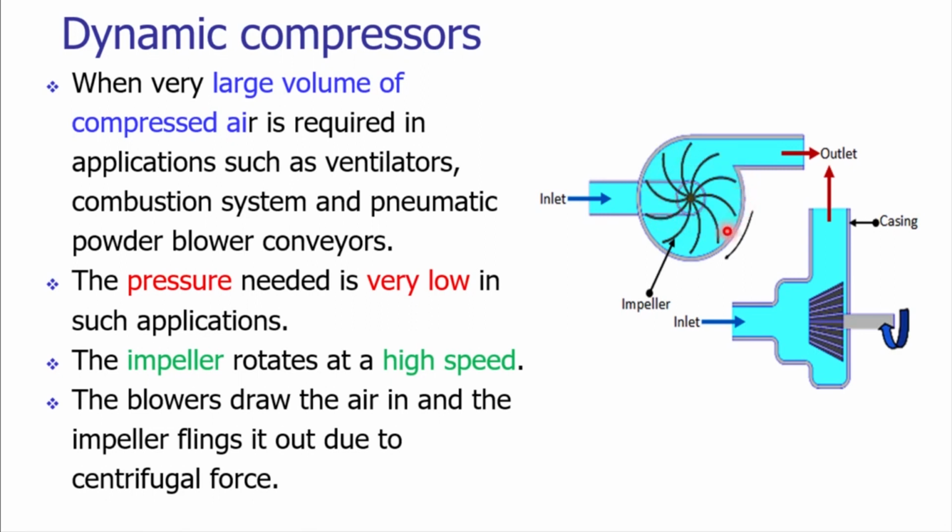As the impeller rotates and we get the input air at ambient pressure, the impellers push the air, and that pushed air with increased pressure will further lead to the outlet. As the impellers are rotating at a high speed, the fluid which has come in would be pushed in a radial outward direction due to the centrifugal force. Air will try to move in a radial direction, but there is a casing, and that casing will restrict its movement in a radial outward direction.